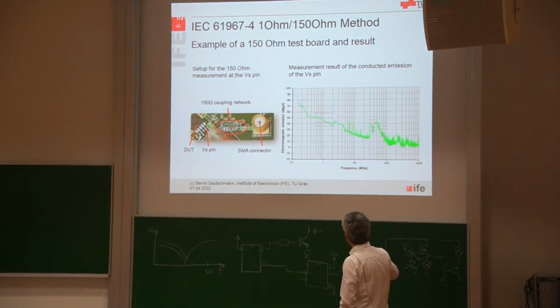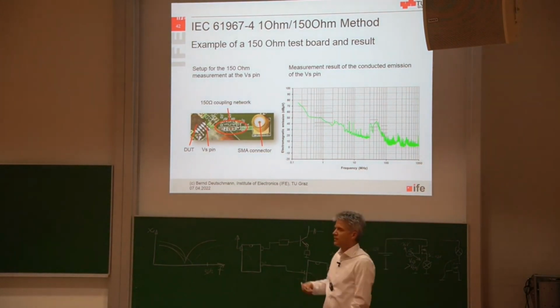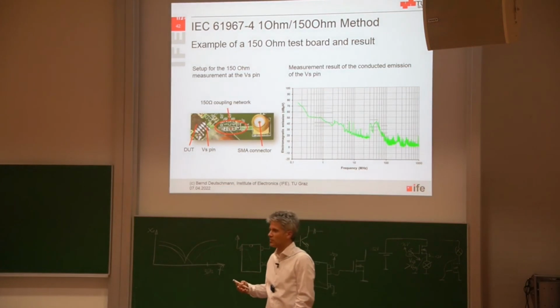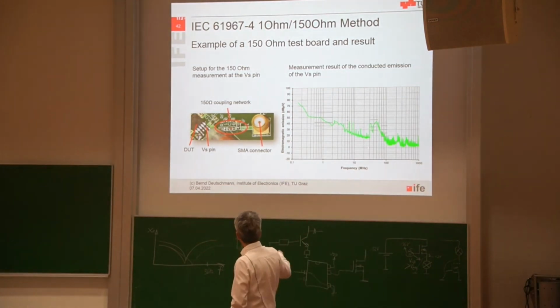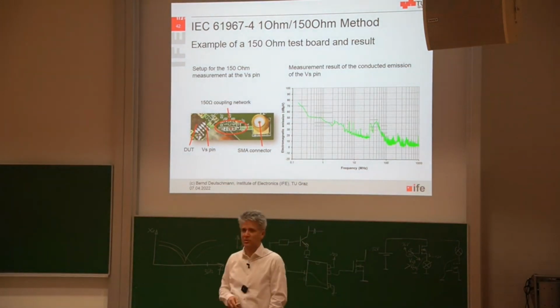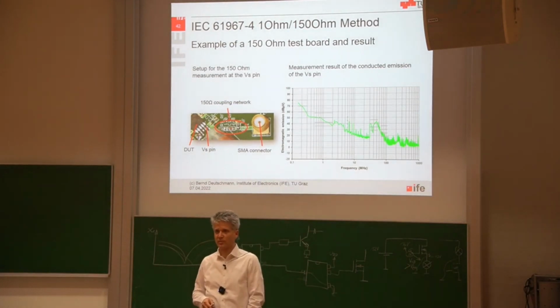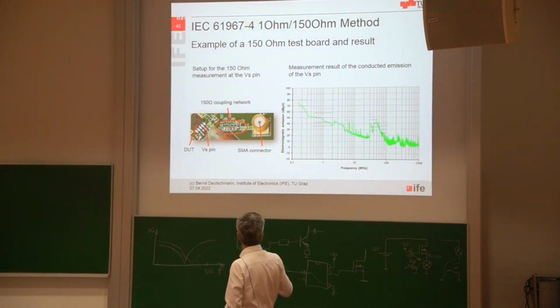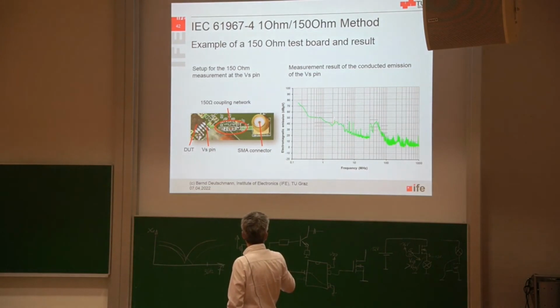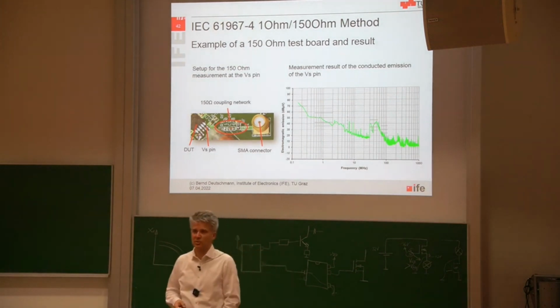But these spikes here that are coming out of my emission, that is caused by the 100 Hertz switching activity, is mainly related to the electromagnetic emission that is generated by the charge pump. Because the charge pump in this case is operated at 2 point something megahertz, and here we can see all the harmonics of this charge pump switching frequency.